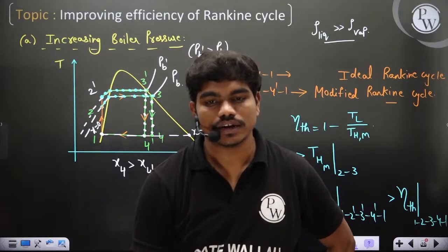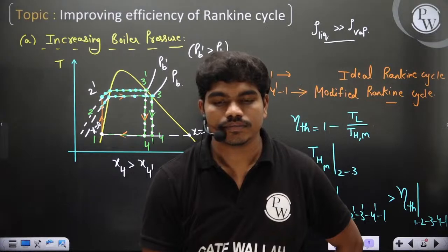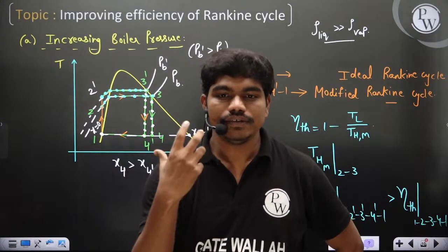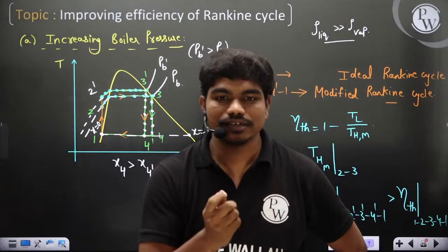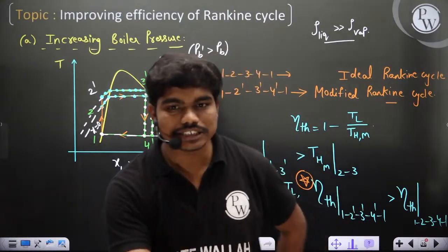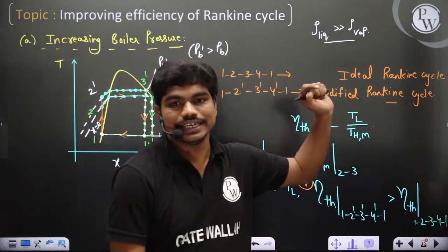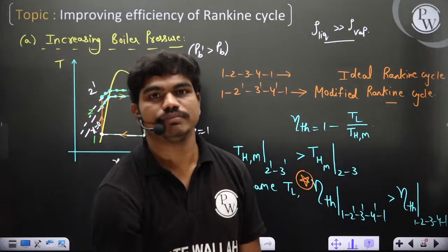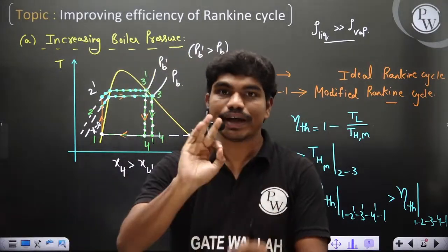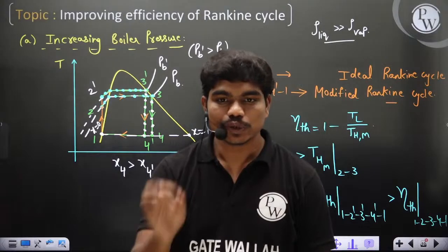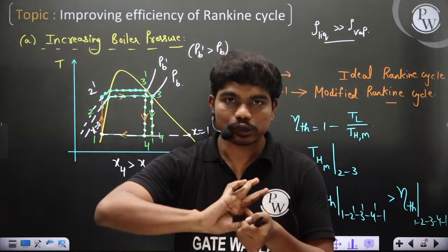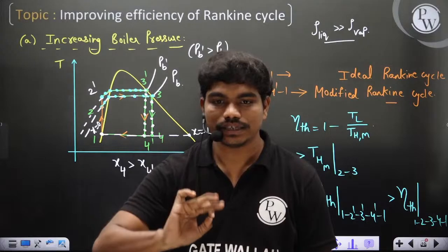Steel or cotton? Steel ball, correct? Because hitting with steel will definitely cause higher damage. The reason is, even though both are of the same mass, clearly density is more for steel. So if high density particles are hitting the blades of the turbine, the turbine blades will get eroded. So low dryness fraction in the case of turbines is very dangerous. The erosion can happen at such levels where